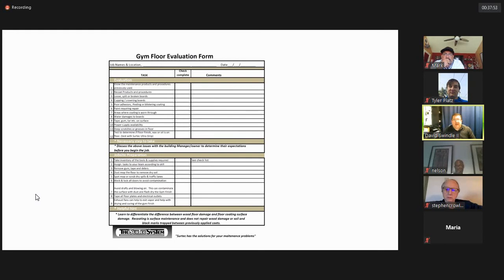Labor Day weekend, and this is probably my worst Labor Day weekend of my life. We had to strip a urethane coating off this floor. And guys, stripping urethane coating is not the same as stripping floor wax. We were using scraper tools and a product that's like a paint stripper that gels on the top, and you have to let it bubble up the finish and scrape it off and scoop it up with shovels.